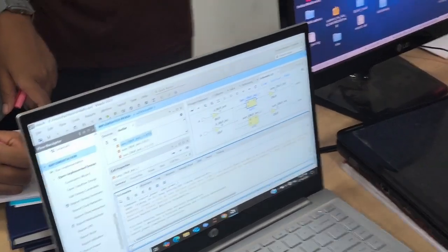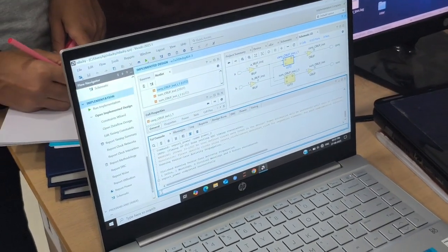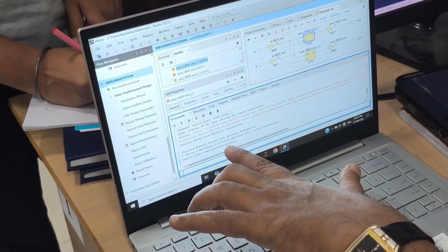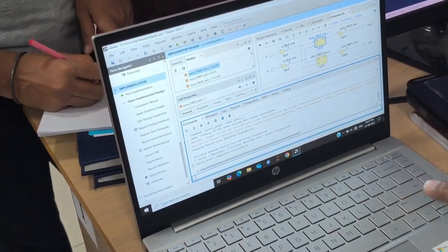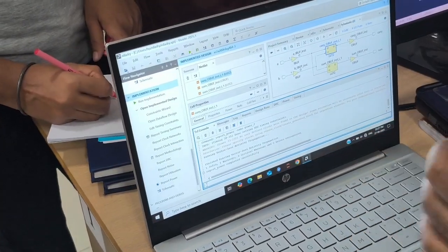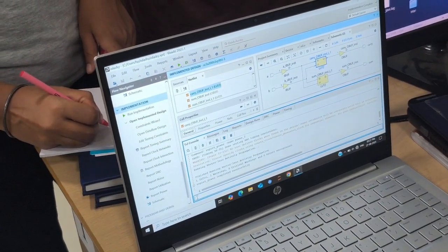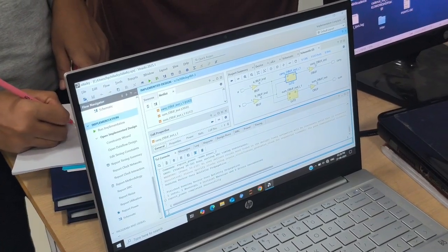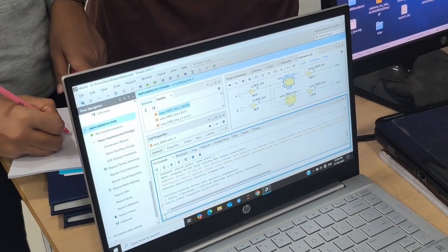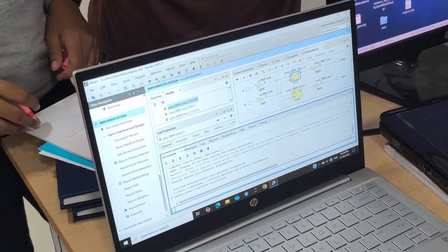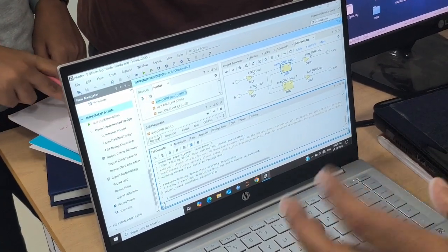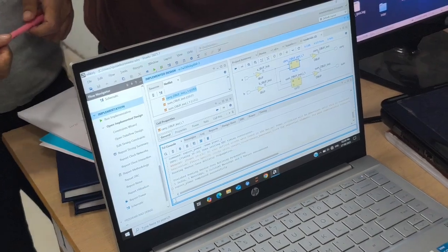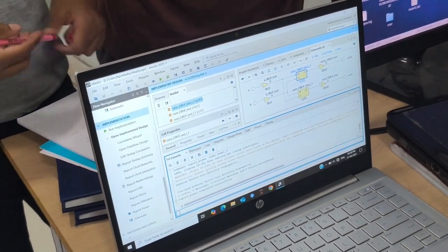And in ASIC, there is another technique called VDD scaling. Here you cannot handle it because the LVCMOS model is already taken, so the input power and ground values it will take automatically. But in ASIC you can change that value. You give the value as power scaling, and then you can reduce the VDD and ground.